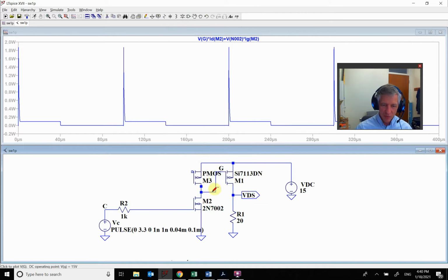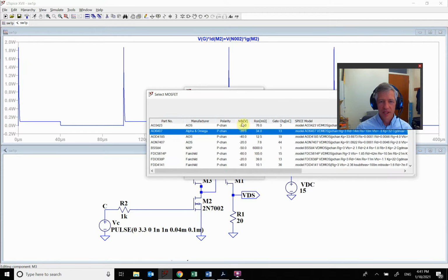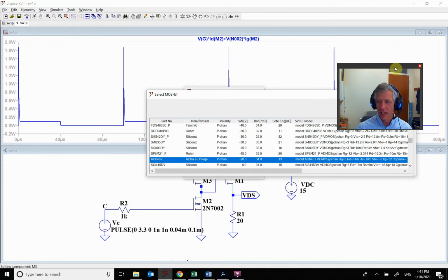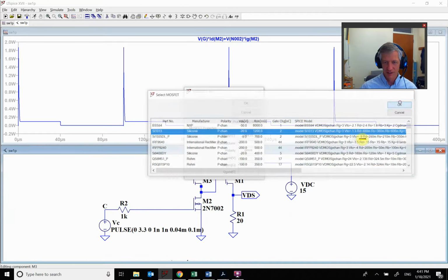So you see now when this one switches, these are basically acting like an inverter. So this point is either tied up here through that one, or it's tied down here. So these are going to be switching at different times. If this one's on, this one's off, and vice versa. So we just need a small transistor here. Again, we want to do something that can handle something that's nice. The small transistors tend to have these large R-ons. So let's just grab this one.